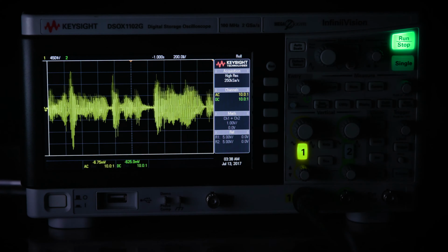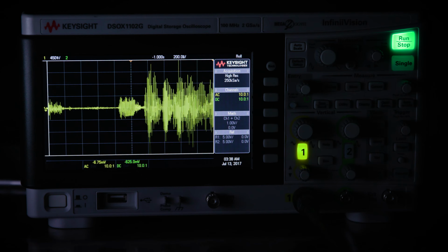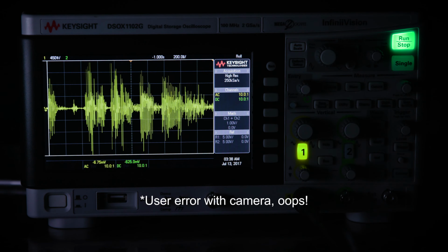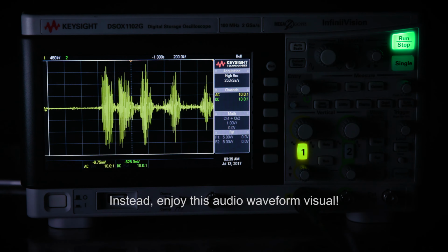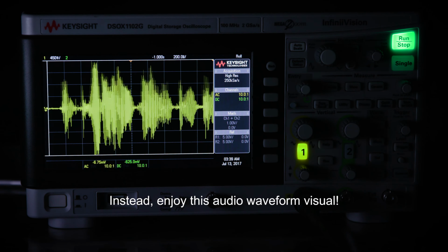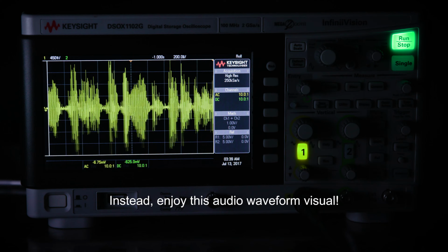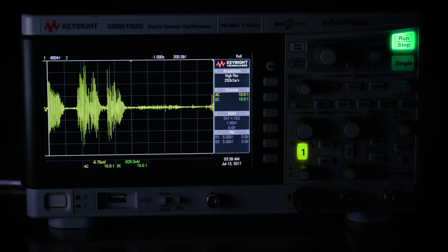But what's missed often is that it's both those things that allow you to accurately make a time measurement. You can have the best, highest sample rate in the world, but unless you have low noise as well, you can't tell where that edge placement is. And having low noise gets harder and harder as you have more and more bandwidth, because noise is proportional to your bandwidth. So it's getting the right combination of those two things that's important in ADC design.